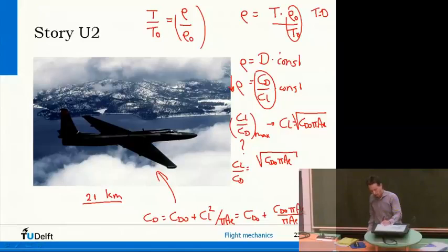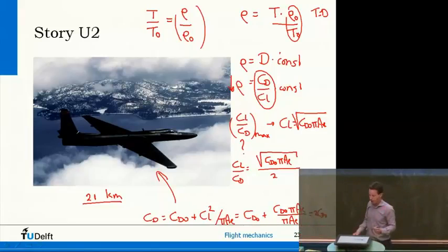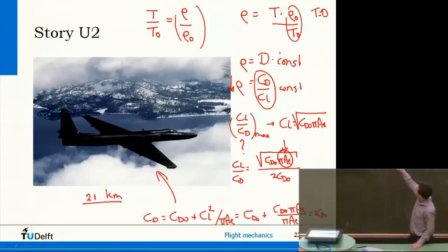Now, you don't have to do this yourself. All I want to show is that this parameter shows you how high you can fly. So you can see straight away that in here, if this A is very large, then that means you can fly higher. So this plane is almost like a glider. It has very long wings for a given surface area. So it behaves like a glider. And if you try to put this plane down on the ground, you have to make a lot of effort to get back on the ground because it keeps on floating.